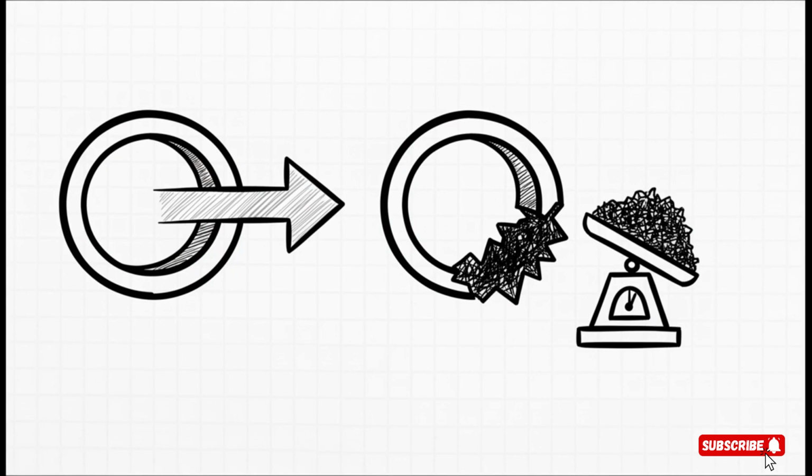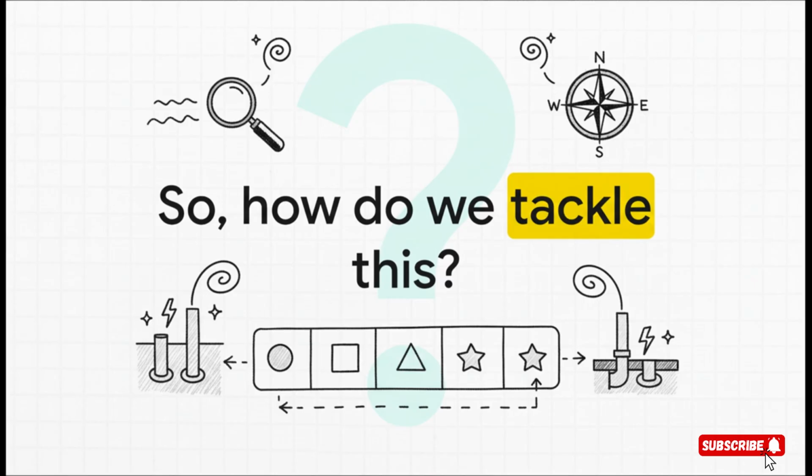And if you want to know just how bad it can get, well, Faraday's law lays it out in pretty stark terms. Just look at this. A single amp, just one, of DC stray current jumping off a steel pipe can eat away 20 pounds of steel in a single year. That's not a pinhole leak we're talking about. That is aggressive, rapid metal loss that can lead to a catastrophic failure way faster than you'd expect. So how do we fight this? Well, you can't just go in swinging. It's not about guesswork. It's about being a detective.